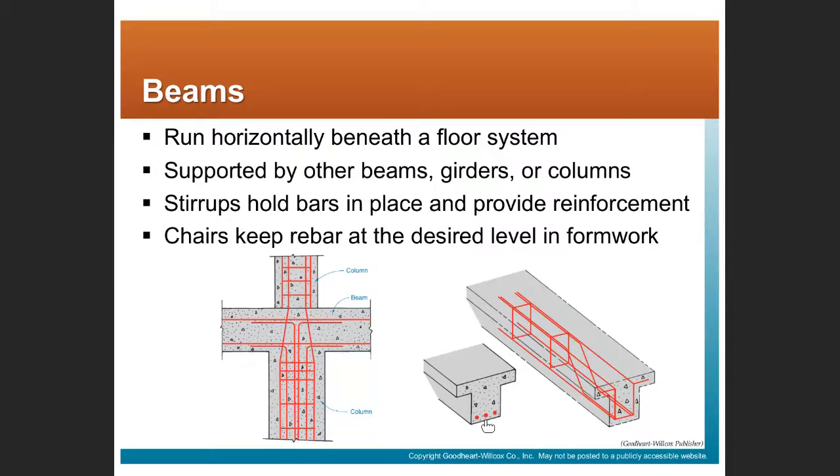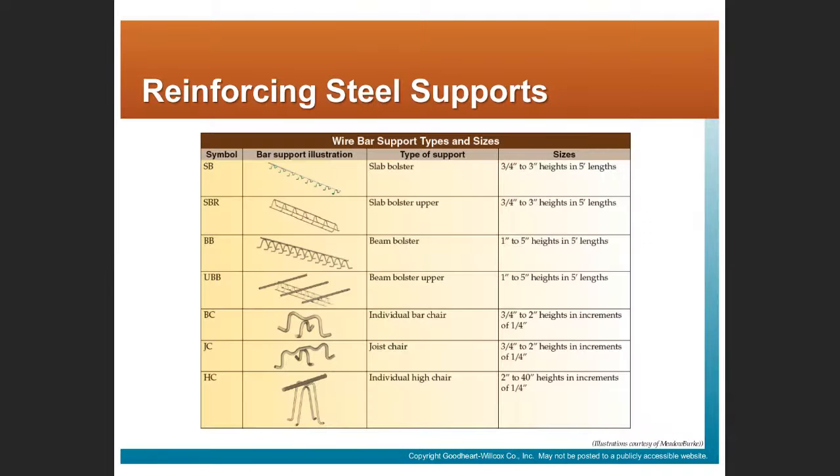The structural engineer doesn't want the rebar at the bottom of the beam. The structural engineer may want that rebar to be 3 or 4 inches from the bottom of the beam. So these other pieces will make sure that rebar ends up in the correct elevation.